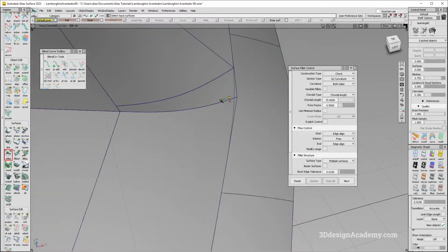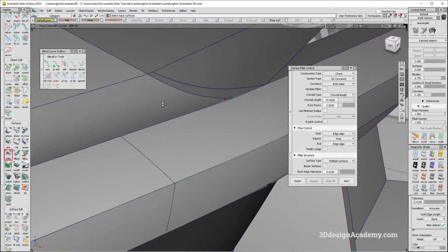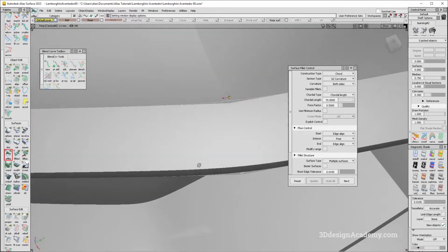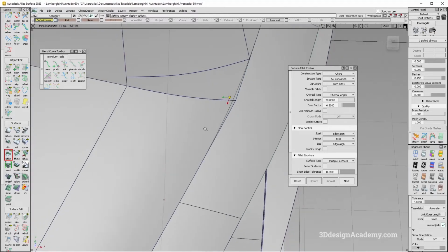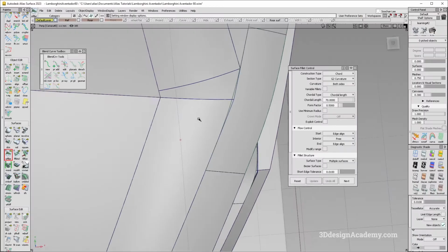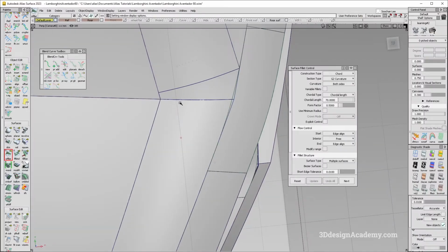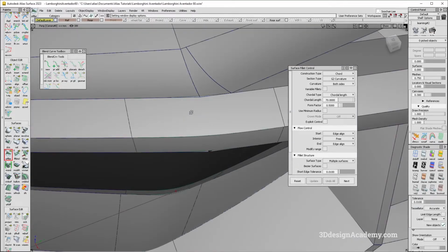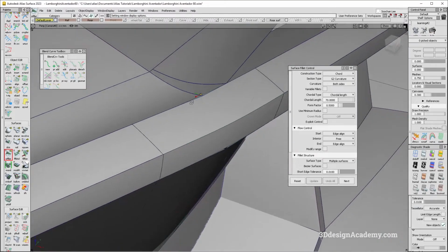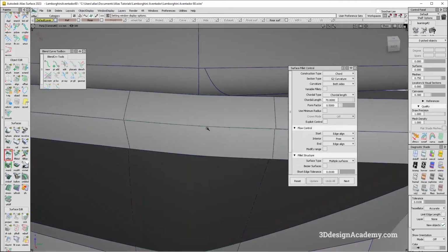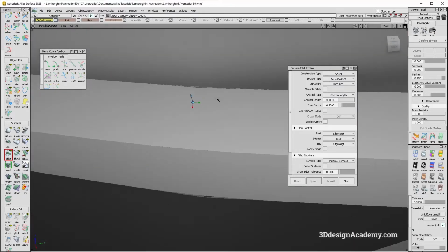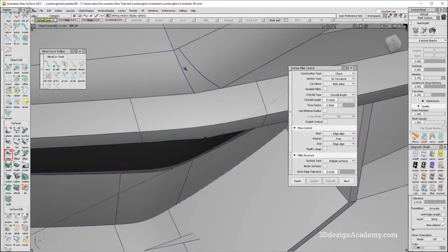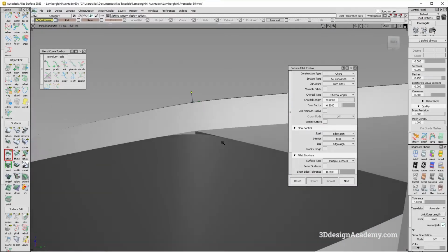Actually, with how it's intersecting, I'm pretty sure I can just intersect it and it'll not be that bad. The only thing I have to do is make a fanning sort of fillet over here to make this a little bit smoother. If the angle was more severe, this would have taken more work, but because the difference is so slight, I think I can get away with just putting a fillet there. We'll have to see.